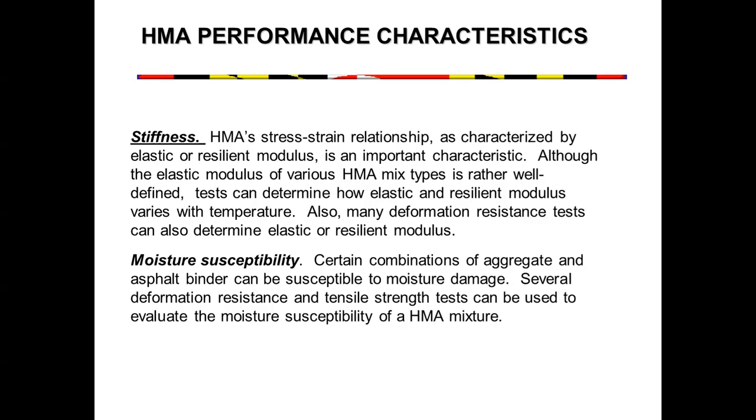Our pavement also fails because of moisture. So we need to test our pavement mixture against moisture as well. There are certain combinations of aggregates and asphalt binders that can be susceptible to moisture damage. This surface deformation resistant tensile strength can also be used to evaluate the moisture susceptibility of HMA mixture.